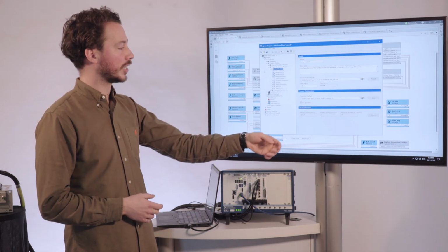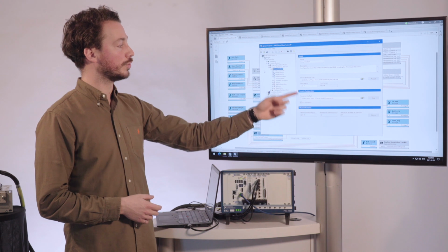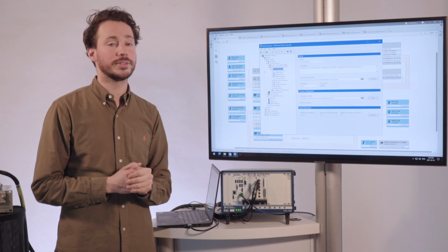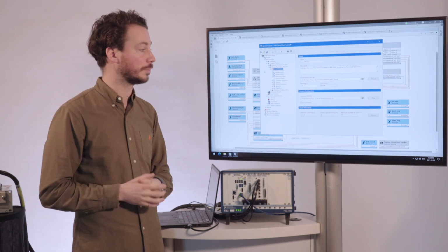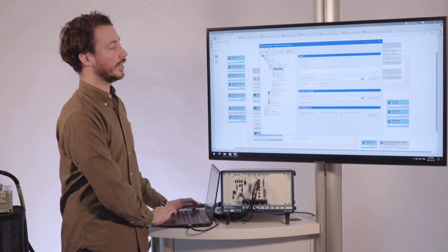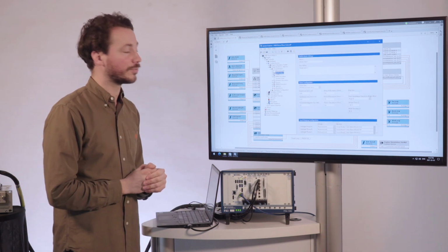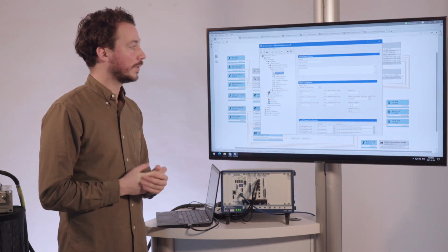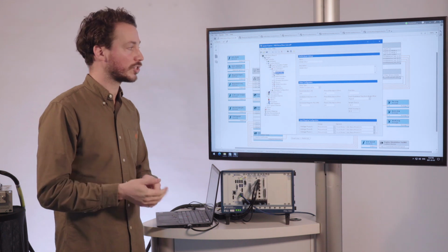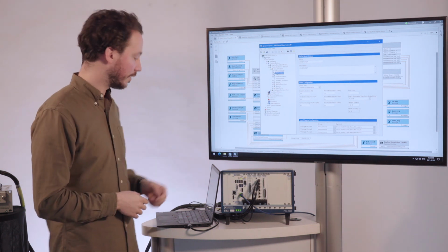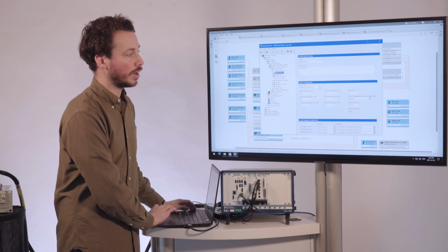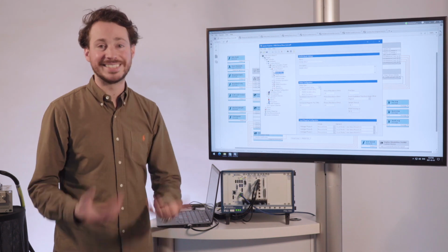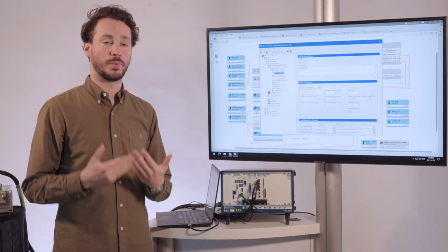And you have certain things such as the number of scenarios you can use. This is where you define your scenarios. And you can see that it requires a time step of, in this case, only 210 nanoseconds, which is extremely, extremely fast. As we continue down the tree, we can see that this bit file, this firmware, supports a dual PMSM machine setup. In our demonstration, we were only using one, but there's nothing stopping us from using two. And as you can see, we have different motor configuration types. So if you want constant LDLQ, if you want variable LDLQ, if you want to simulate a BLDC, we can all do that from this window.